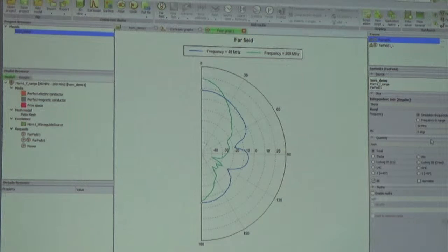And this ratio is decided by the impedance of the antenna, how well it is matched to the rest of the system. And these antennas, or antennas in general, are not matched. So whenever there is an incidence, a part of it will always be reflected back and the rest of it will be transmitted. There is very little loss because most of the antennas are metallic, right? So the losses are very small.